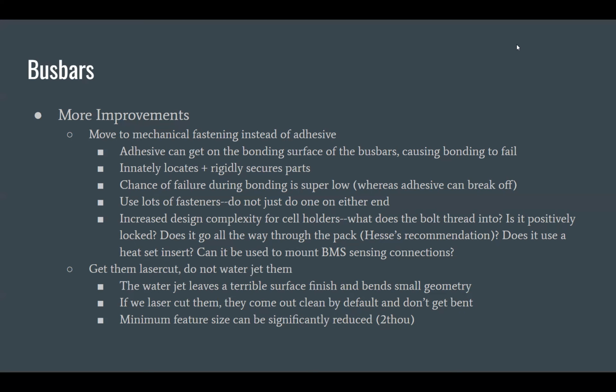That means we have these energy limitations where we can't store more than a certain amount of energy per chunk of the battery, and that's why we have to split it up. Our battery, for reference, is 8.7 kilowatt hours, and a Tesla is 100 kilowatt hours. So for us, we split it up into chunks of, I think, about 1.4 kilowatt hours, and then you add those together.